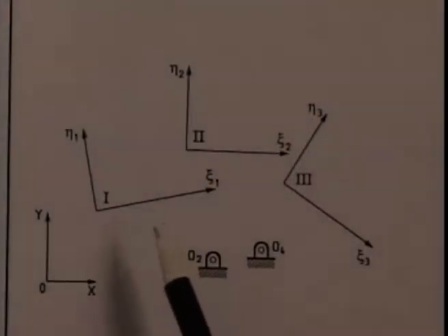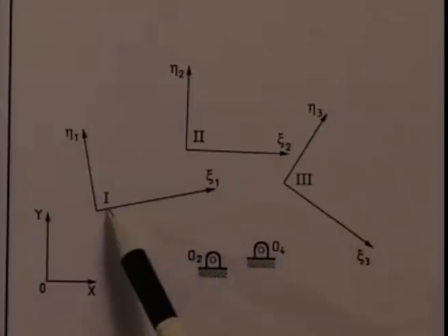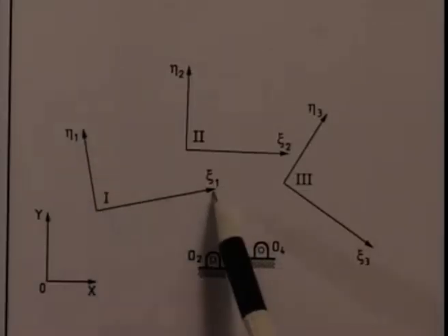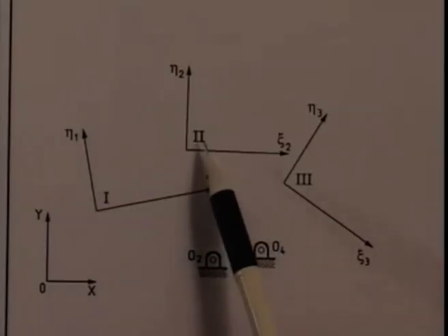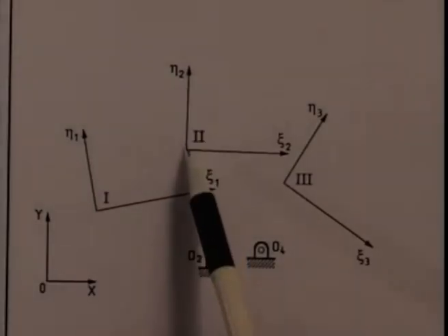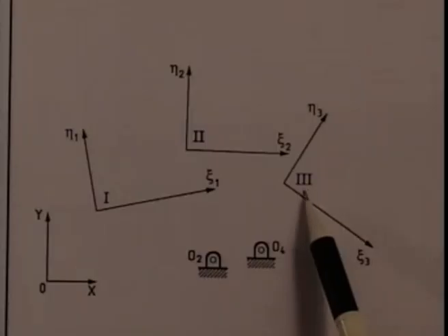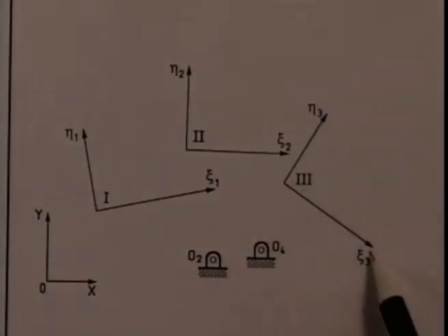So to determine the moving hinges on the coupler, we consider the same relative movement between the coupler and the fixed link, but we hold the coupler fixed and allow the original fixed link, or the ground link or frame, to move. We shall now explain this with the help of an example. Let the 3 positions of the coupler be prescribed by eta 1, zeta 1, this is position 1. These coordinate axes are fixed on the coupler. The second position of the coupler is given by position 2 when this eta, zeta takes up the position eta 2, zeta 2. Similarly, this is the third position with eta 3, zeta 3.